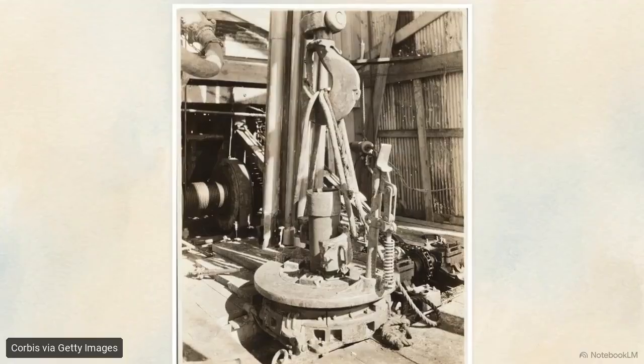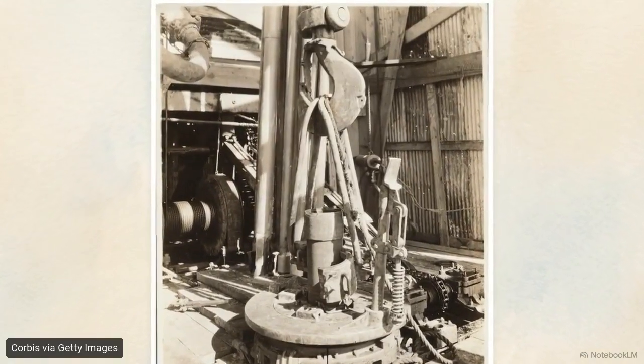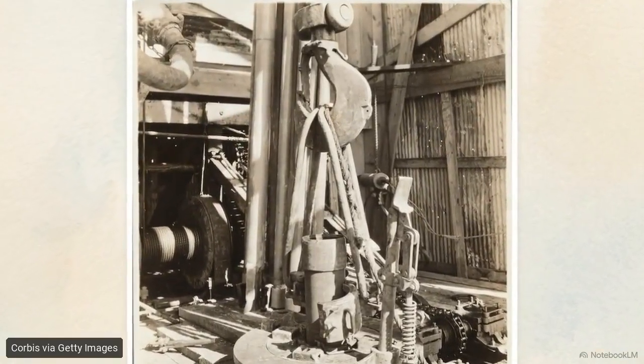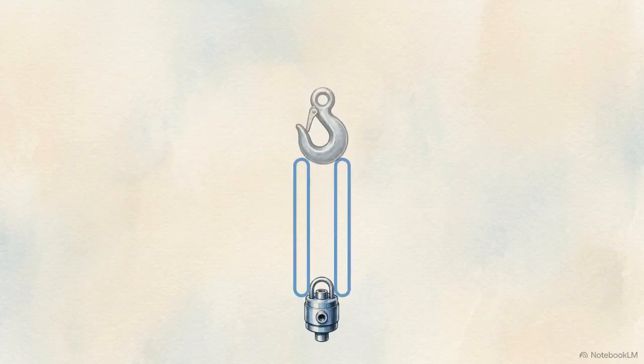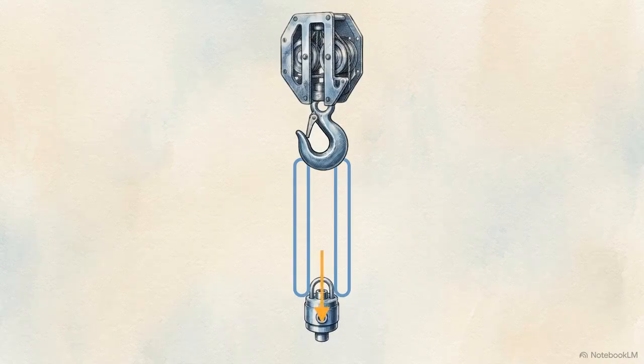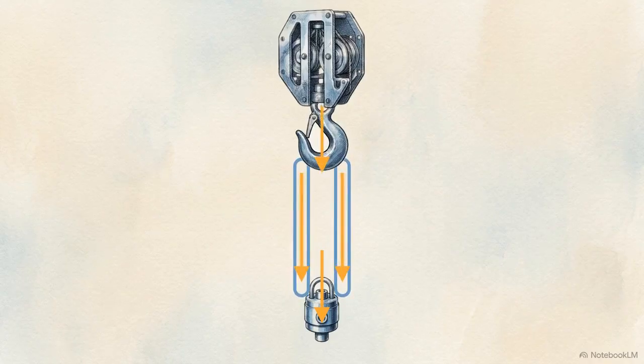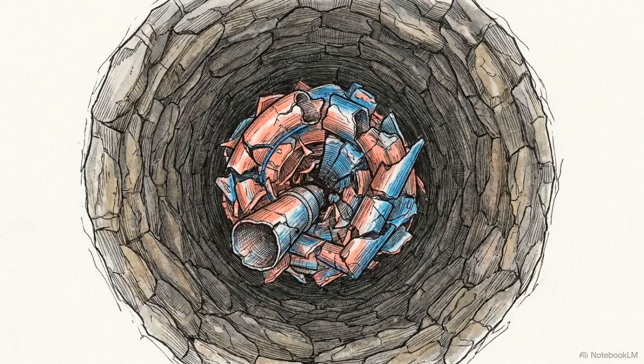The load path flows through a precise sequence of structural links. The drill string hangs from the swivel. The swivel is supported by the bales. The bales hang from the hook, which transfers the entire load into the traveling block. If any single link in this chain fails, hundreds of tons of steel plummet to the bottom of the hole.